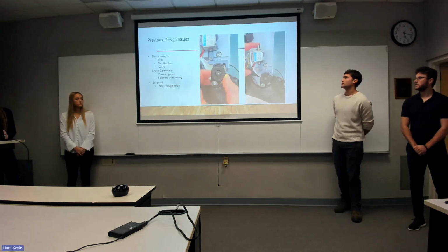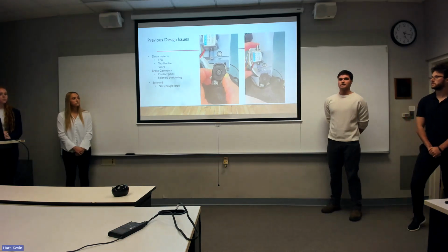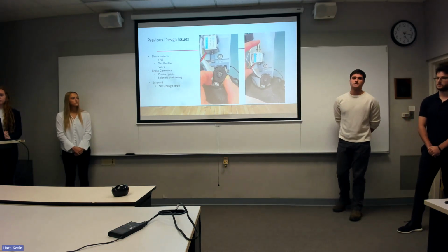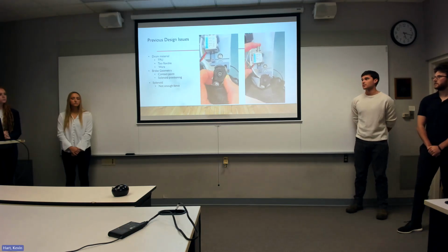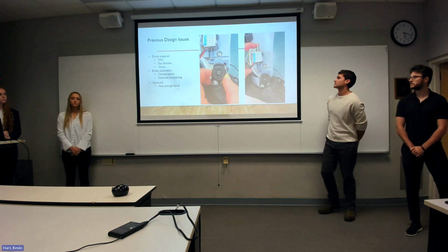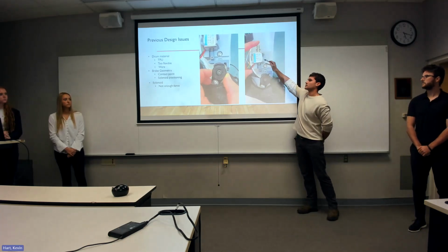And then the solenoid, so right here, this is the plunger that I'm pushing on. The stroke length of the plunger is inversely proportional to the force that it produces. So a shorter stroke length means much larger force. So this can definitely be moved closer, so we could shorten the stroke length.